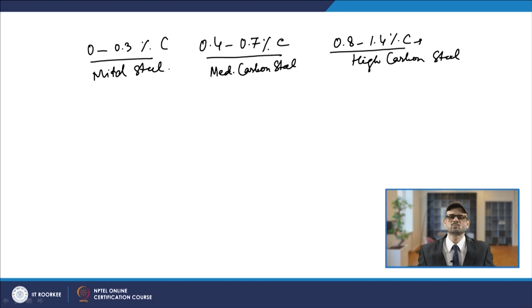And if you need ductility, white cast iron cannot otherwise be used, but when you malleabilize it, when you give it the annealing treatment, then you can use it for automobile components, because it develops good ductility and malleability. And in the case of SG iron, which is found only in the cast form, it has a good combination of strength as well as ductility.